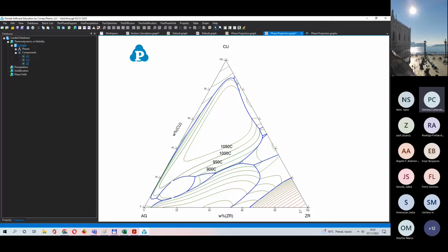This we will see. For the moment, we don't need it, but we could be interested to do isothermal sections. So you can do it in such a way, you can do isothermal sections there. You can do it quite easily. I want to see them from 500 basically to 700. Number of steps, not that many. Select 3 steps, otherwise it will take too long.